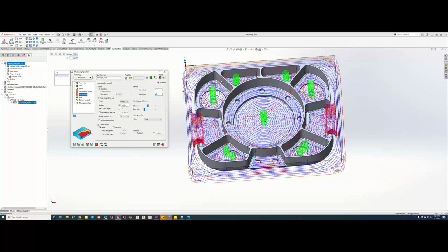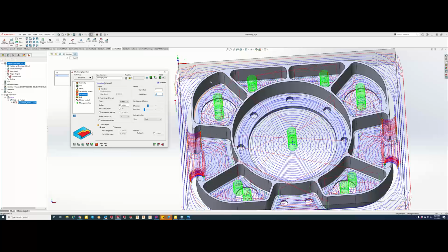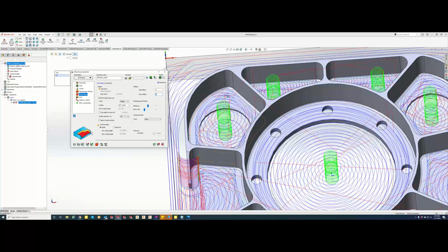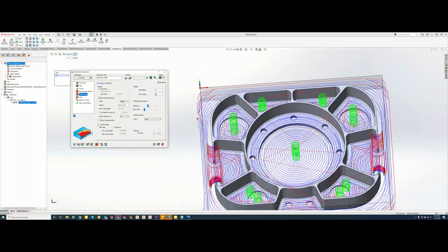In some areas, like when we're arcing off and arcing on, we may have just tiny little witness marks there, right? Because when we come back, usually with a 2D iMachining finishing pass, we get that one nice, smooth, constant finish all the way around our geometry. Here, you can see we're still arcing on, arcing off, getting that material removed out of there as fast as we can.